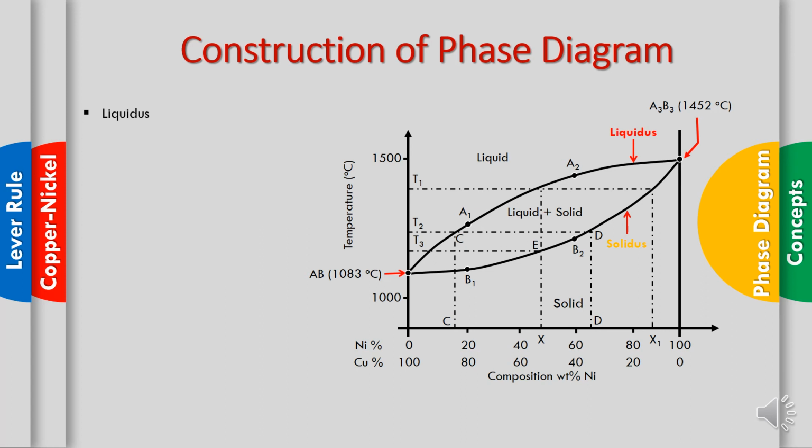The line of the liquidus and solidus is placed something like this, whereby from the projection, if we fix the composition, we can project to get the temperature. And at the temperature we set, we can project to get the composition.